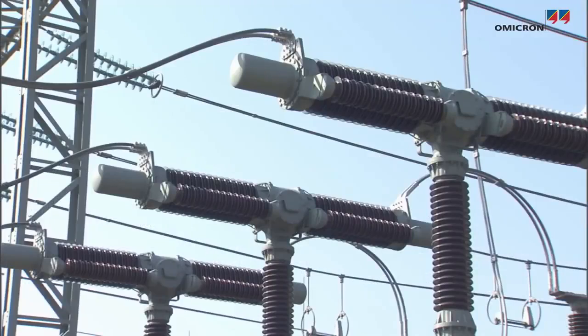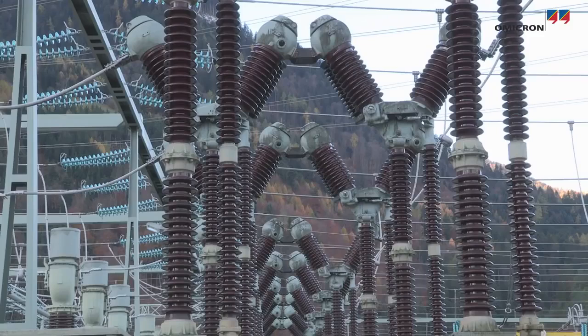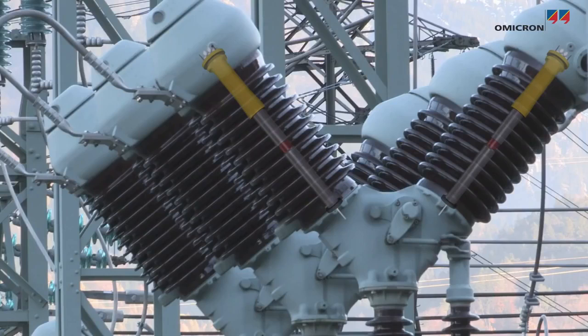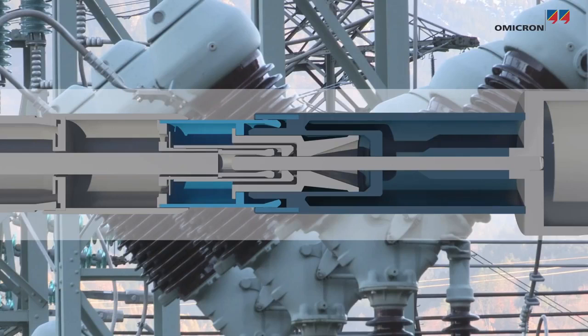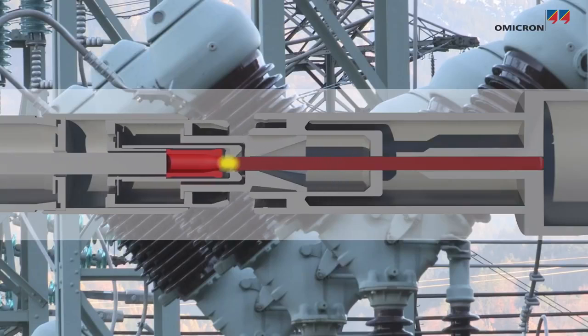Different circuit breaker technologies are in use, depending on voltage level, application, and the age of their design. Current interruption takes place in interrupter chambers containing air, oil, SF6, or a vacuum. Circuit breakers may use multiple contact systems consisting of main contacts and arcing contacts. The main contacts allow operating current to flow with minimal losses, while arcing contacts can break short-circuit currents with minimal arcing erosion.